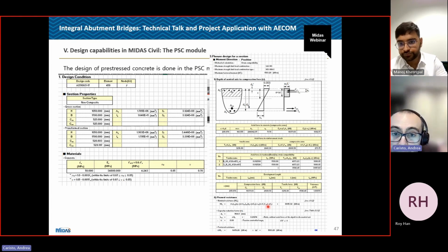Particularly in the SLS check for cracking, where we allow the concrete to go beyond the maximum tensile resistance, and we allow for the normal reinforcement to pick up an extra 200 MPa in this project. You need to define that there. So yes, it's there. As you can imagine, the governing check is usually at transfer.